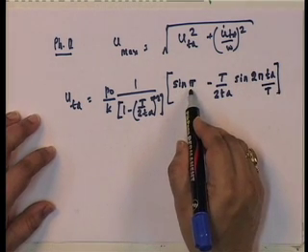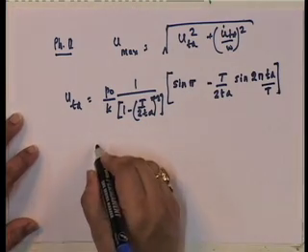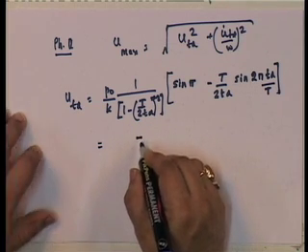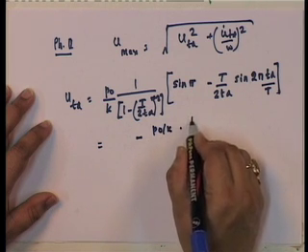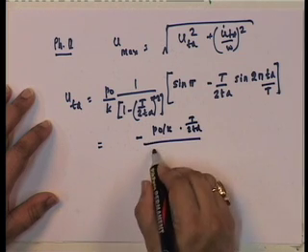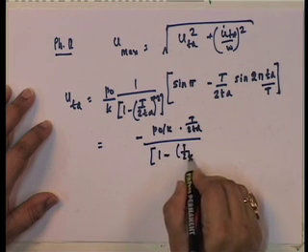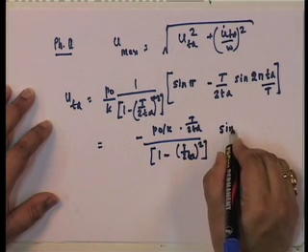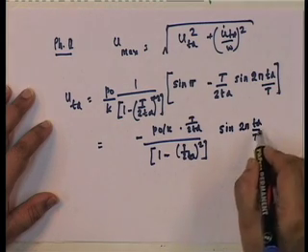Okay. So, what is sine of pi? It is 0. So, what we get is u of t_d is equal to minus P naught by k into (t upon 2 t_d) all over (1 minus (t upon 2 t_d) squared) into sine of 2 pi t_d by t.